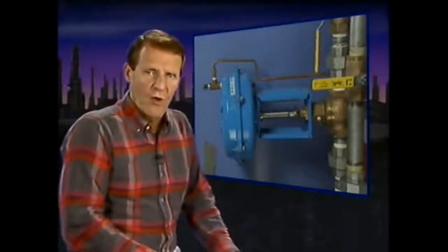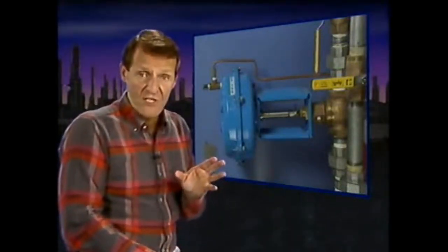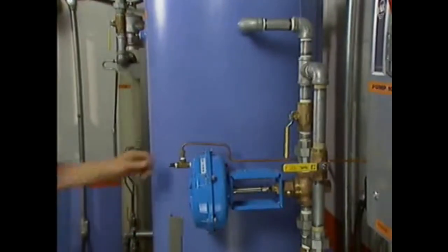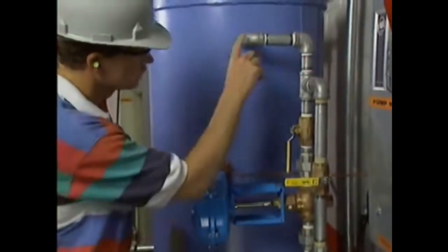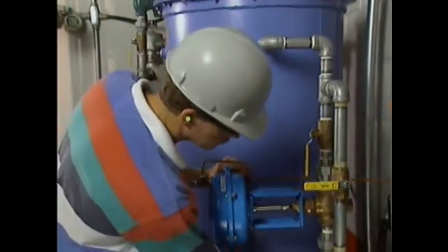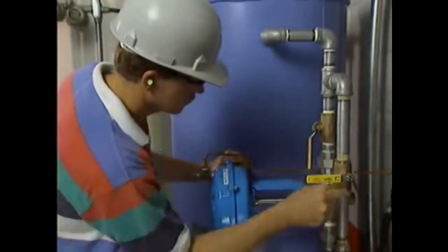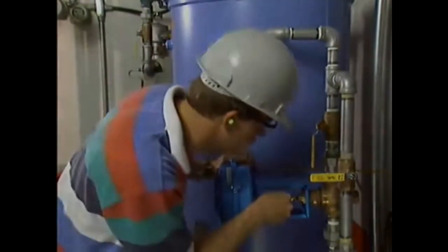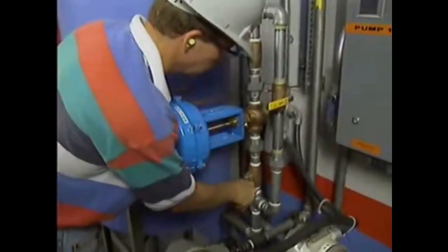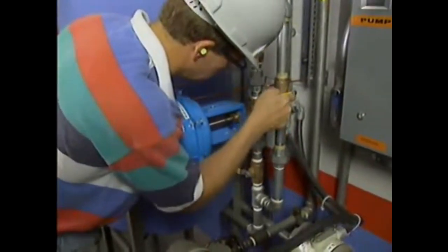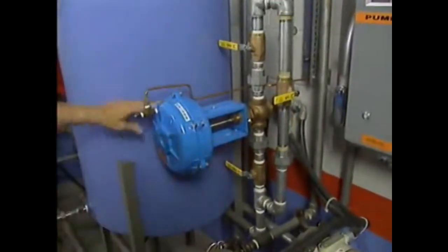To find the cause of the problem, the outside operator inspects the recirculation line control valve for obvious signs of damage or problem. When he inspects the valve, he can find no signs of obvious damage to the valve or the valve operator. Also, the local valve position indicator shows that the valve is shut, so the outside operator believes that the valve must be leaking by its seat. To correct the problem, the outside operator isolates the valve and reports the valve to the maintenance department for repair.